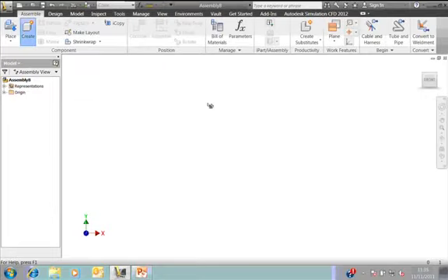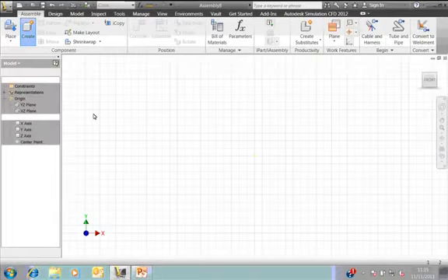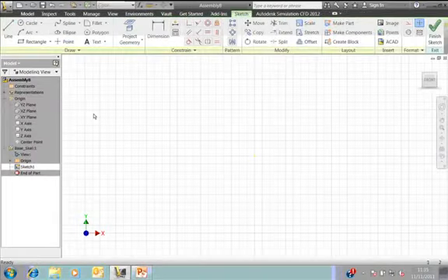The other thing that you need to do when creating in-place components in assemblies is, we used to say, well, just click on the screen to sketch on the XY plane. The problem we have these days is a lot of people have 3D connection manipulators, and it's good practice now really to select the XY plane from the browser instead to place your first sketch. You know then for sure that's on the XY plane. Otherwise you may have problems later on when you push this through to a 2D drawing, and we've had instances where the view is not quite flat on the drawing view.